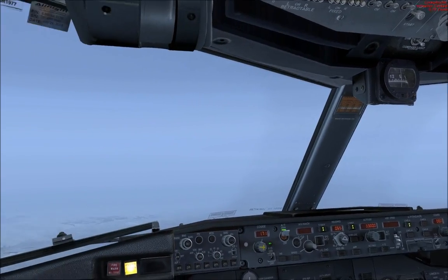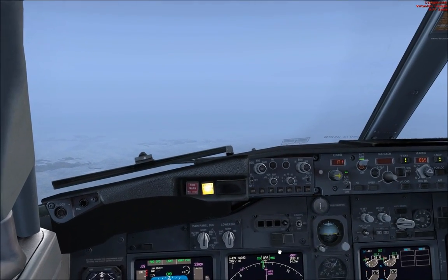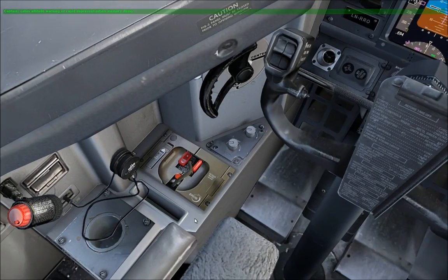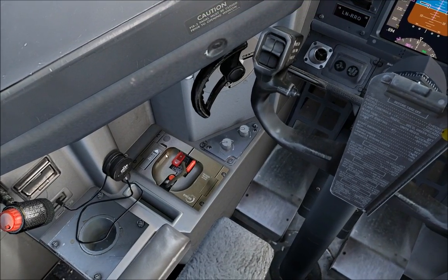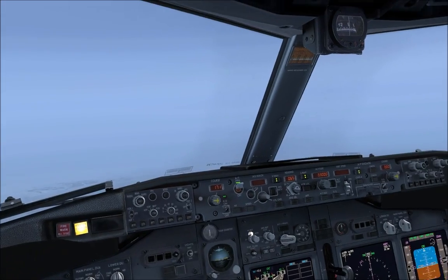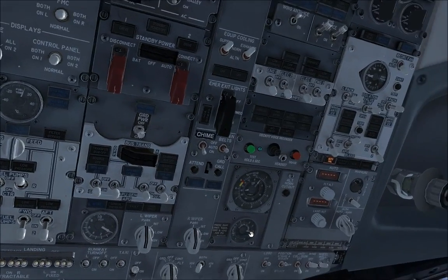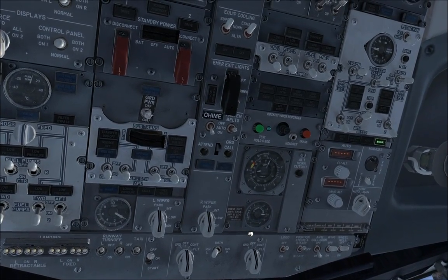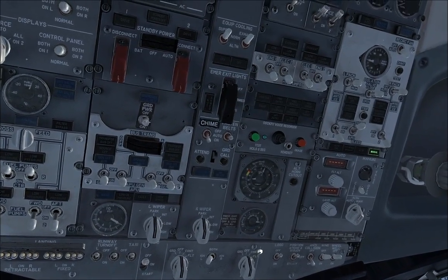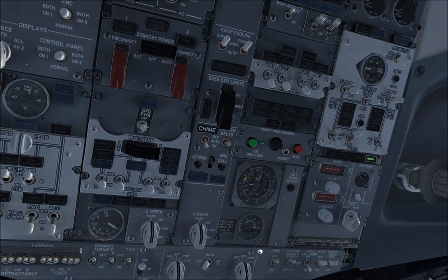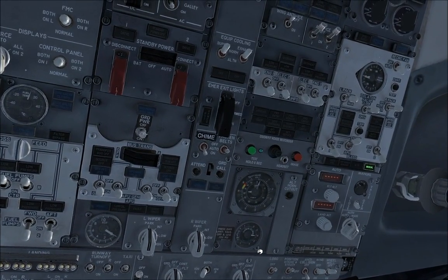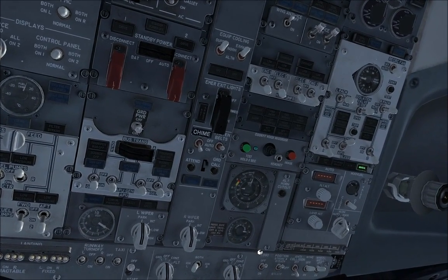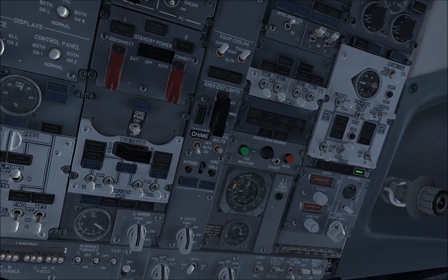Okay, master caution, air conditioning. Cabin altitude warning or rapid depressurization memory items. Check. Cabin altitude warning or rapid depressurization checklist. Condition: one or more of these occur. Cabin altitude exceedance. In flight, the intermittent cabin altitude configuration warning horn sounds and the cabin altitude lights, if installed and operative, illuminate. Okay, the memory items: don oxygen masks and set regulators to 100%.